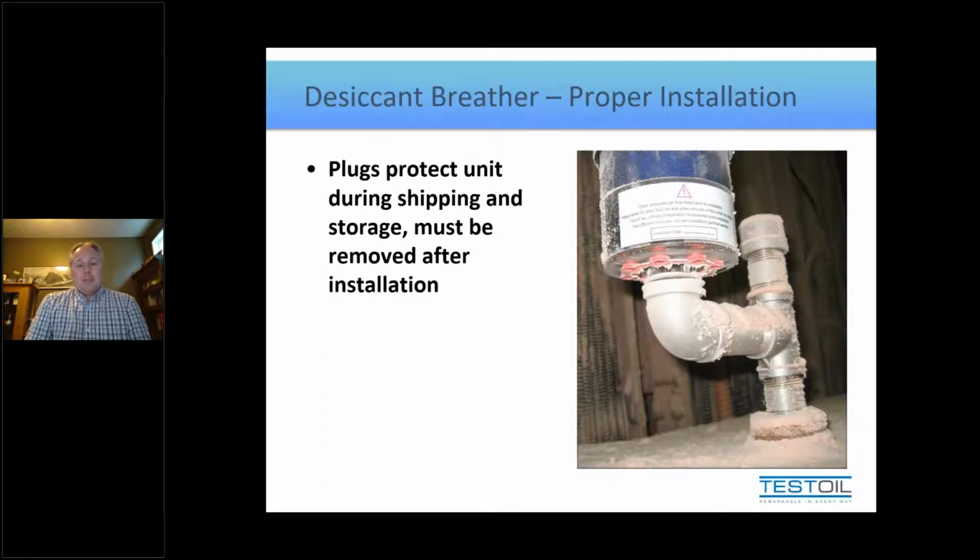With the cubic feet per minute rating, you would say, okay, this is my rating. You'd look it up compared to the breather you have. It would tell you to remove 2 plugs, 3 plugs, 4 plugs, however many it was. And people would do this. And therefore, thinking they were maximizing the performance of the breather, after a few months, they'd pull out a few more plugs.